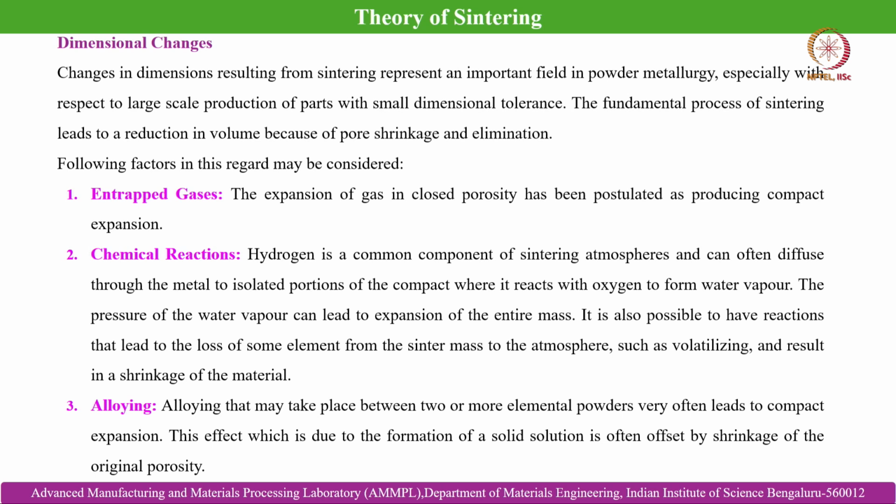However, the sintering associated densification that happens in the powder aggregate negates the effect of the increase in volume due to these chemical reactions and even the entrapped gases. So the net dimensional change we often see is negative, that is shrinkage, because the densification rate predominates over the effect of the gas entrapment or chemical reactions. And then the third is alloying.